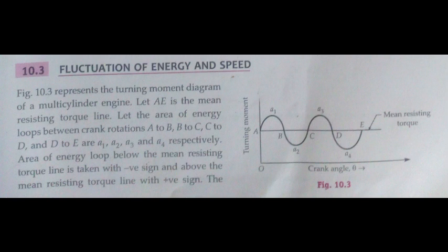So first of all, for fluctuation of energy, in the figure we have been given a figure of turning moment diagram of a multi-cylinder engine. So this is a turning moment diagram of a multi-cylinder engine. Now you can see turning moment diagram is a torque versus crank angle.